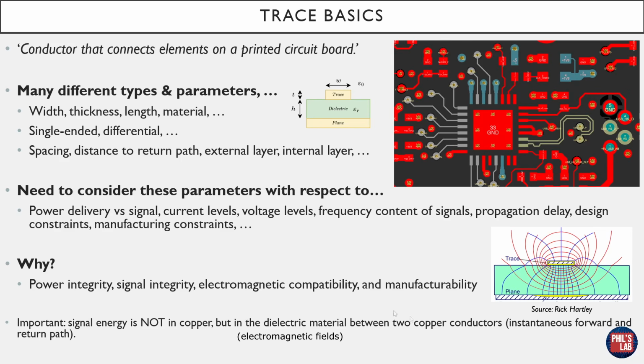You'll hear me saying this in other videos as well, but I'd like to reiterate the point that a trace is not a singular element. We typically always have a forward path and a return path, and the electrical energy is actually contained in the dielectric space around or between these traces.